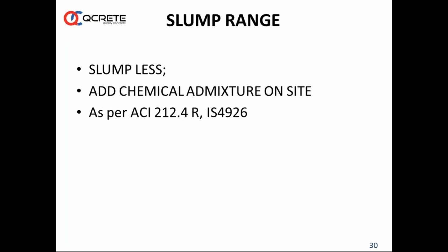The only thing that we have to take care of here is that we need to remix the concrete thoroughly and not unload, because if you suddenly unload, it may cause segregation. This is already recommended in ACI, and also in IS 4926. A.M. Neville has written a lot about this in Properties of Concrete, and many other authors have also written about this.